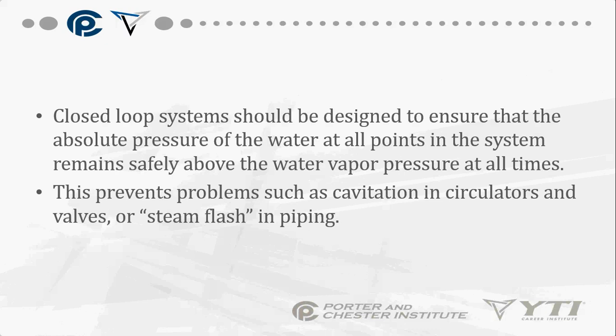That could be a couple of things. That could be an expansion tank that is no longer good, because remember, the expansion tank allows for the water to expand. If I have no place for water to expand, what's going to happen with the pressure inside my boiler? It's going to rise. It's going to increase because the water has no place to go. It's sealed, guys. It's closed loop. So the only way for it to escape is going to be through the relief valve.